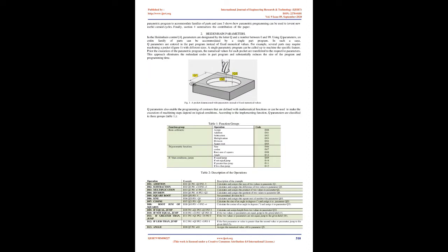1. Introduction. The operation of a CNC machine tool is controlled by a program written in the G/M code programming language called part program. A part program contains an ordered sequence of statements specifying in detail the cutter motions to be executed and the auxiliary operations, e.g., spindle on/off, spindle speed and feed rate, to be realized by the CNC machine in order to machine a specified part. A statement is made up of words, characters, and numerical digits are the elements that constitute a word.